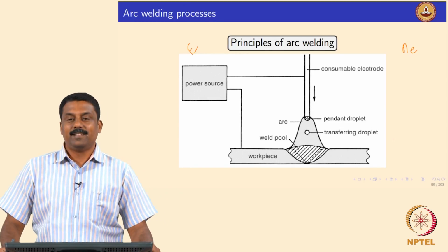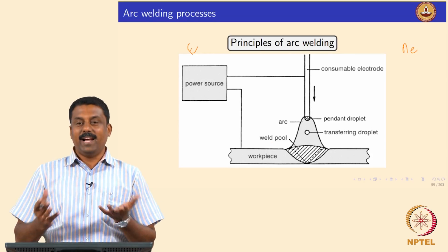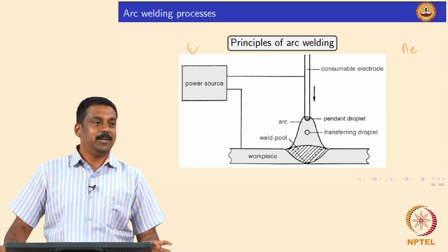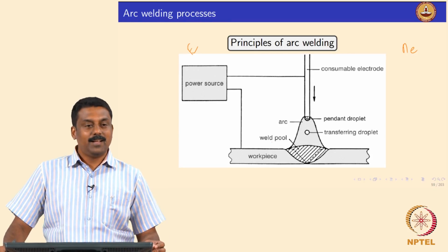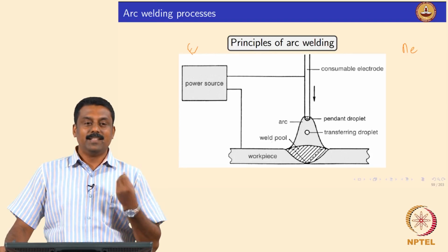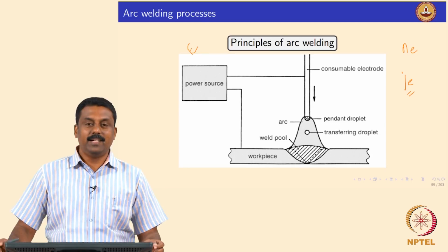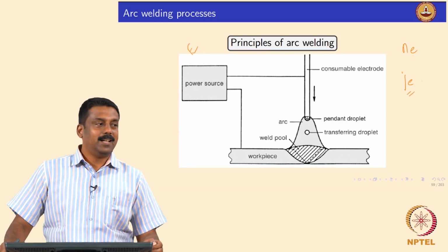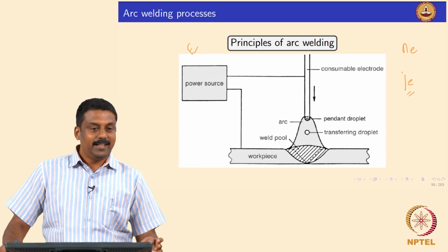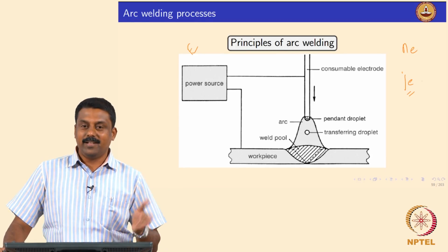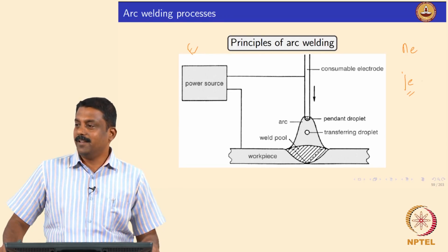During this process you also need a gas which can be ionized, so that you can strike an arc, and once you strike an arc, the process itself, the ionization, would determine the heat generation by the term JE. And from JE you generate heat, and the heat is transferred by conduction, convection and radiation. So this is the physics of arc welding.